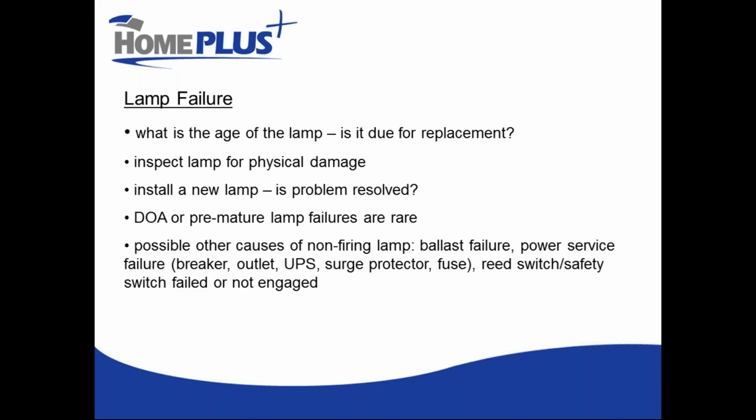The good manufacturers have prevented that by putting fail-safe mechanisms in place that won't allow the lamp to fire unless the lamp harness is connected properly to the lamp and the lamp is inside its chamber. So there are some of these devices that if they are just a little bit out of alignment, they won't make that proper connection on the basis of, hey, this might not be plugged in correctly, so I'm not going to take a chance.